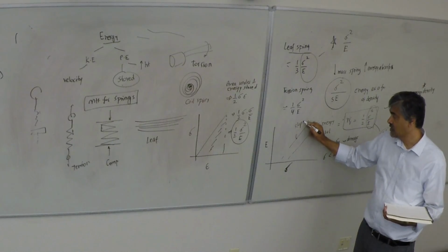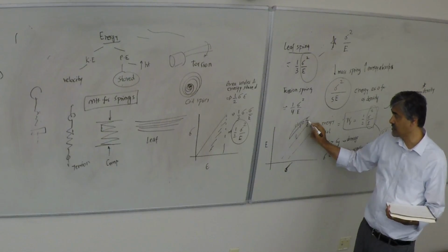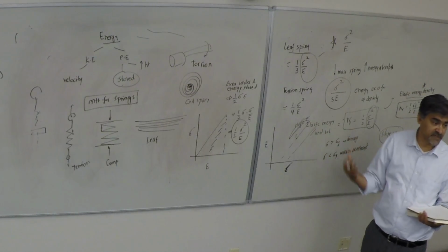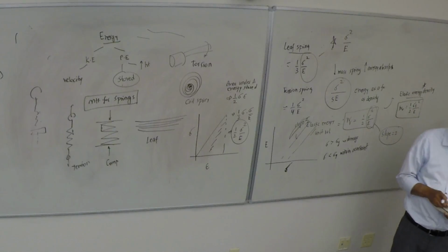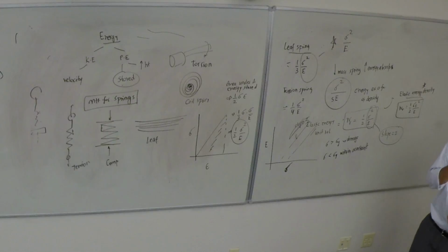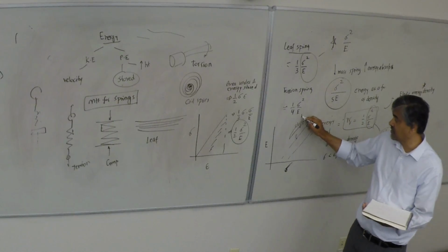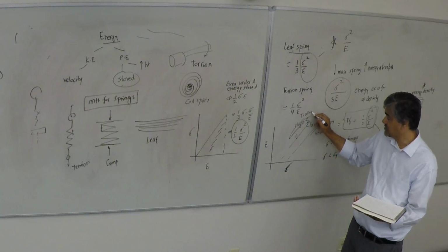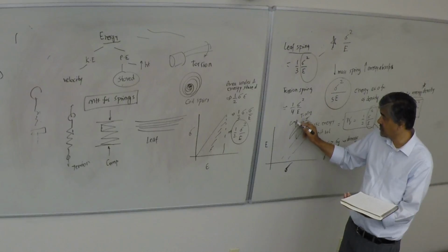And then, since you're maximizing this, you're looking for material choices up in this range and see what those are for a given spring. So that is what it would be. And the options that you come across are things like titanium alloys. You may come across composites here. You may come across spring steel.